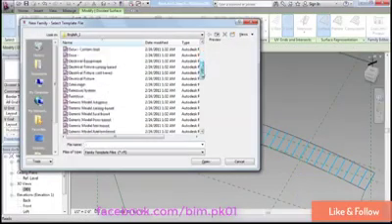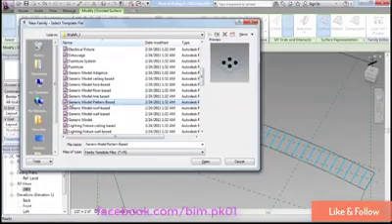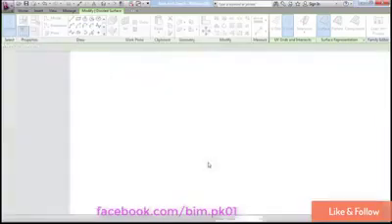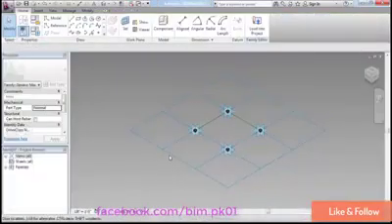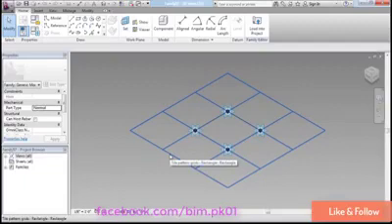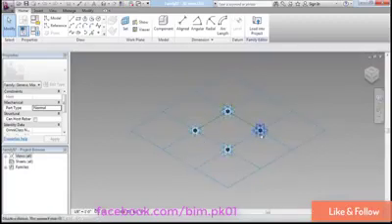Scroll down. And this time I want the generic model pattern-based family template. It's got the gray background, so it is part of the massing environment. And you get this surface out here, and you can see that this is just sort of like all hosted family templates. This is just sort of a temporary surface for your use in constructing the geometry. So this represents the surface that we'll be creating in our project. And they've got this one square in the middle accentuated by these reference lines and these points. And that's the controlling geometry that's going to control the shape of this object.